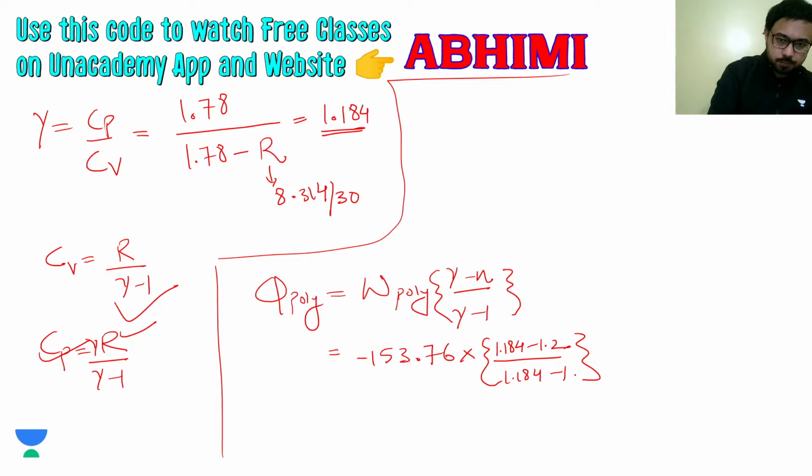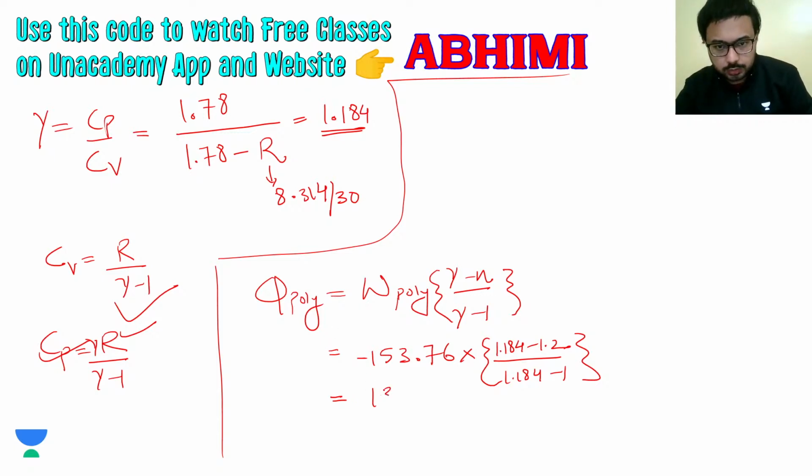So the answer that is coming out here is 13.37, and it will be a positive value because work polytropic was negative and this term will be negative because gamma is less than n.